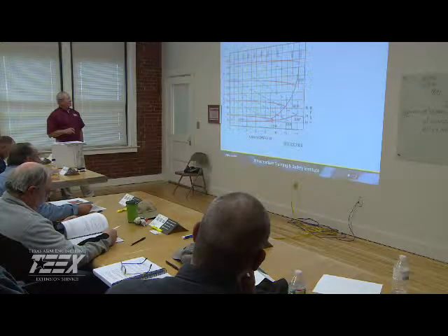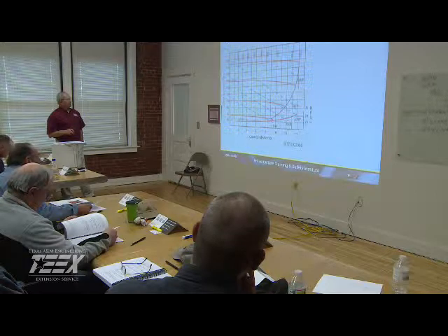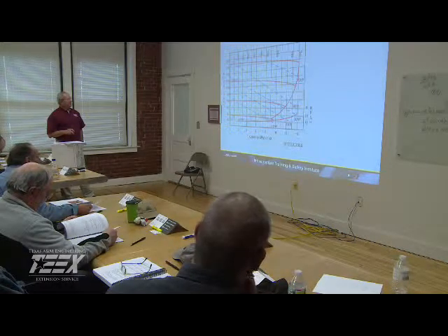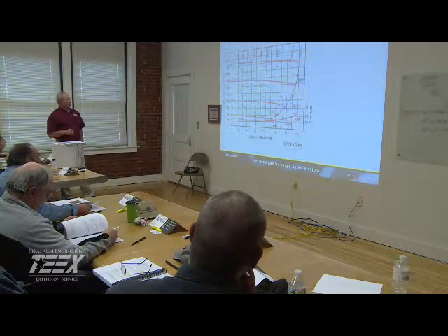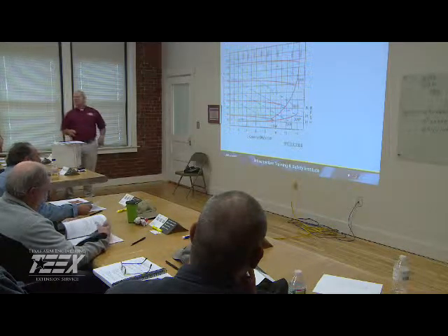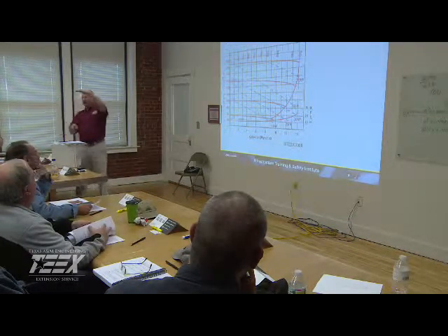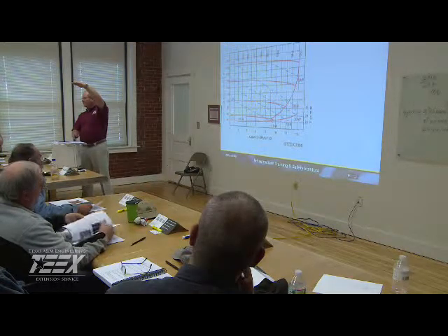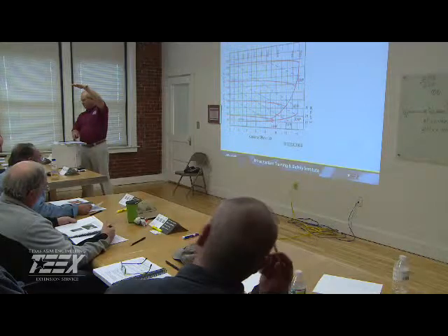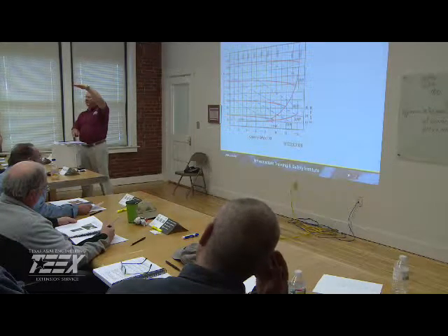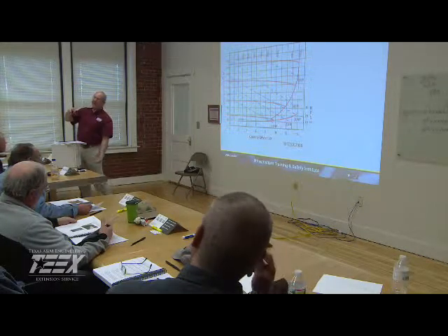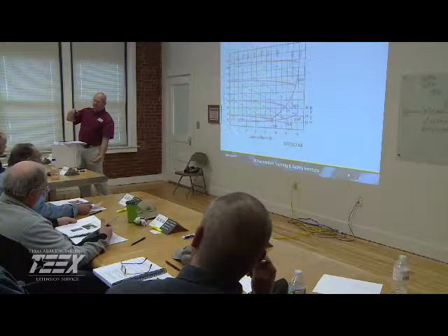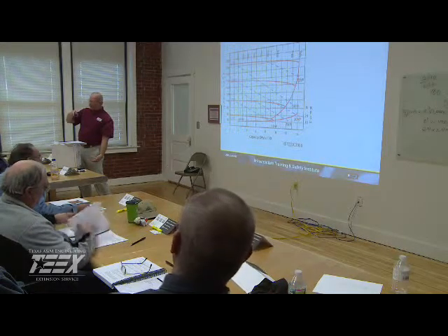My net positive suction head would be right here, so I'd have to have that minimum of suction head. You draw where it intersects, you come over here, I'd have to have at least 12 feet of net positive. That means to start that pump, I need at least 12 foot of water above the eye of that impeller. Okay? Now, if I have suction lift, I have to have a vacuum that equals that amount of head. A vacuum lift to start that pump.